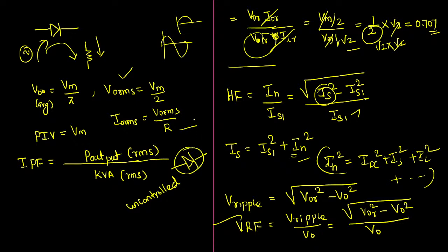Like, now if we take the SCR, with the help of the gate, I can control it. You can say, if gate current is 0, what will happen? If gate current is injected, what will happen? So SCR, though it is having anode and cathode terminals, though we are connecting positive voltage, negative voltage across these two terminals, though we are trying to inject the current, all these parameters, whether the SCR will be turned on or turned off, that will be decided by the gate current only.